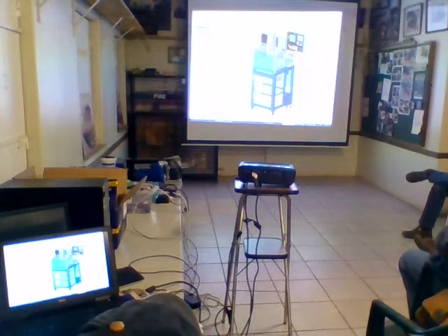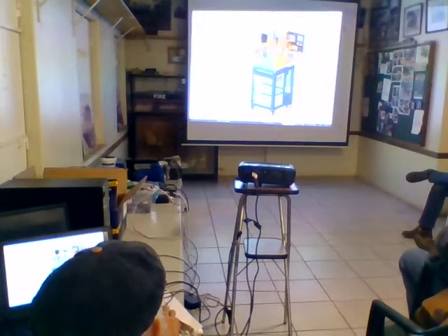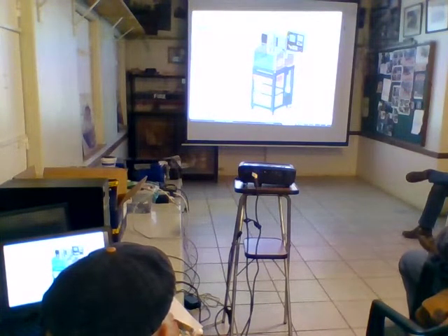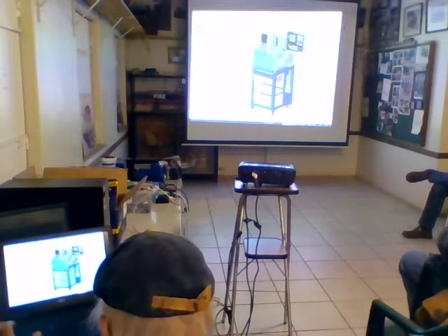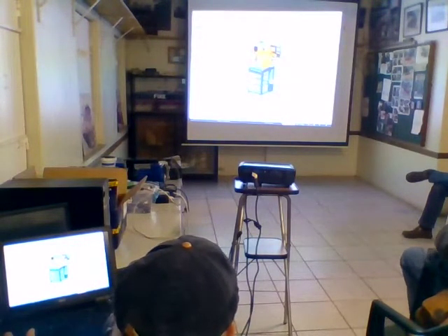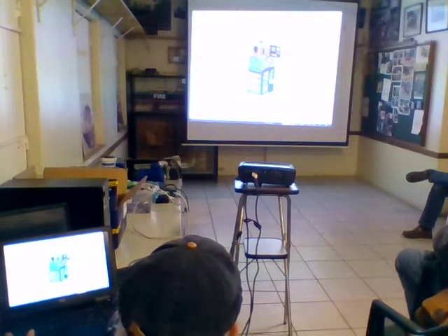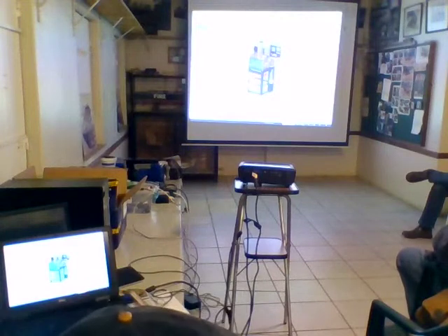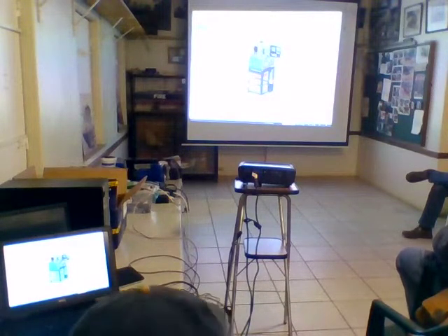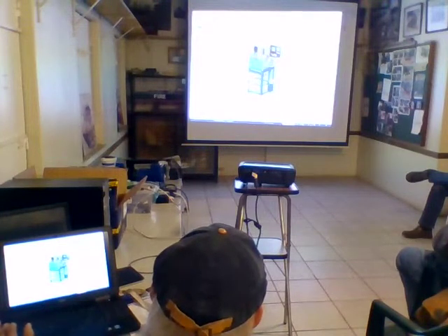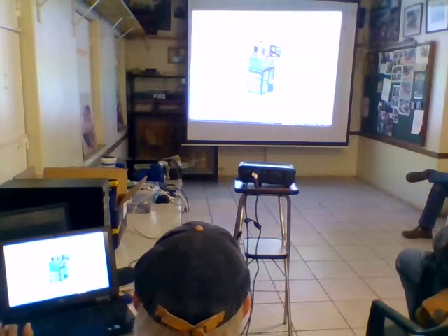So that's the overall picture. The machine is designed to get a 4th axis and a 5th axis into it. I'll show you in a minute. And these are the latest motors that I fitted onto it. Those are Heidenhain motors. There's some guys who say we want a Heidenhain control on it, not a Siemens control. So I just fitted the smallest Heidenhain motor that I can get with a brake onto it, and that's what it looks like.